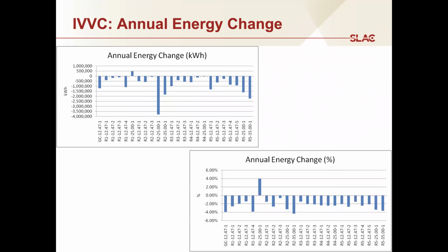And if you look at the energy, it's a similar story, right? You don't always see an energy benefit. In some cases, you see an energy cost associated with deploying it. And so the main takeaway from this study was that if you wanted to deploy volt-VAR control, you might deploy it on, say, only 40% of the feeders, and you would get about 80% of the result. It's not a universally beneficial thing to do. And I think this was an important insight. This paper became the first major contribution that GridLAB-D offered to understanding how smart grid strategies needed to be thoughtfully deployed.